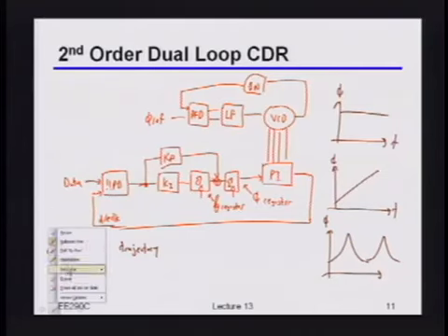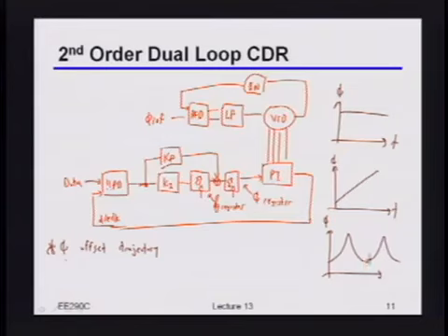Well, if you're going to do that, then that means that indeed your phase is going to have this weird looking behavior on it. And it may even continue and just have these weird circles and things like that. Okay? So again, the key point is that if you know that you're going to have some weird trajectory in the phase, you should build your CDR loop so that it can figure out what all the deterministic components of that trajectory actually are.